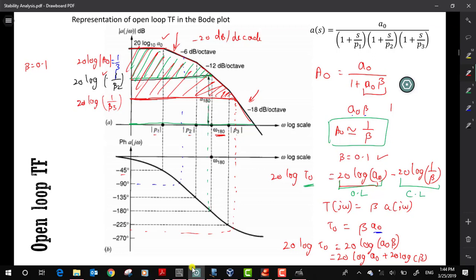Is that clear? For the system that I had written down, this will not work for a feedback factor that is greater than beta 2. After that, the feedback would change into what is known as positive feedback, and the output will keep oscillating. So this is not suitable. I want to design a system so that for whatever beta factor I plug in, I always have negative feedback around it. So that is the motivation for our next session. With that, we'll complete.